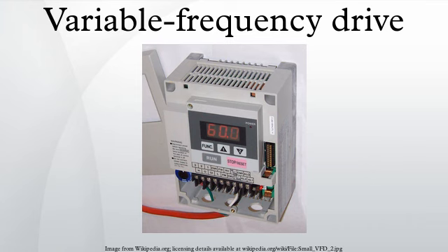Control performance. AC drives are used to bring about process and quality improvements in industrial and commercial applications: acceleration, flow, monitoring, pressure, speed, temperature, tension and torque. Fixed-speed operated loads subject the motor to a high starting torque and to current surges that are up to 8 times the full load current. AC drives instead gradually ramp the motor up to operating speed to lessen mechanical and electrical stress, reducing maintenance and repair costs, and extending the life of the motor and the driven equipment.